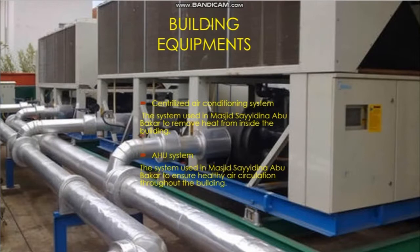It contains a lot of water, which is very dangerous to the bolt connections in the surroundings, because water can induce corrosion, which is very, very dangerous to the equipment, as it can disrupt the balance of the equipment in a way that it can create more vibrations, and as we all know, vibration is the main cause of system failure.